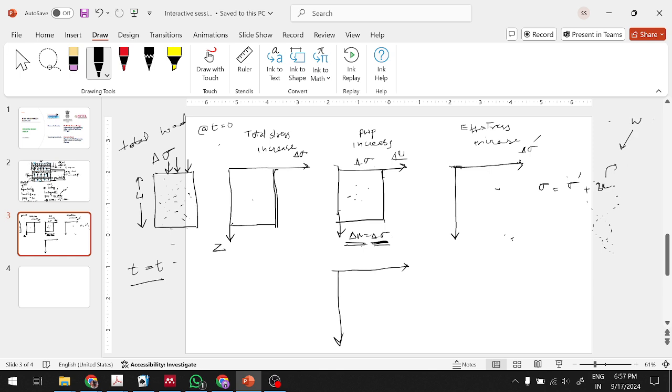That is a totally different branch of unsaturated soil mechanics. In unsaturated soil mechanics, we have two components here. This will be sigma is equivalent to sigma dash plus the pressure due to water plus this is chi, like you factorize it based on the saturation, which is equivalent to volume of water divided by volume of voids.